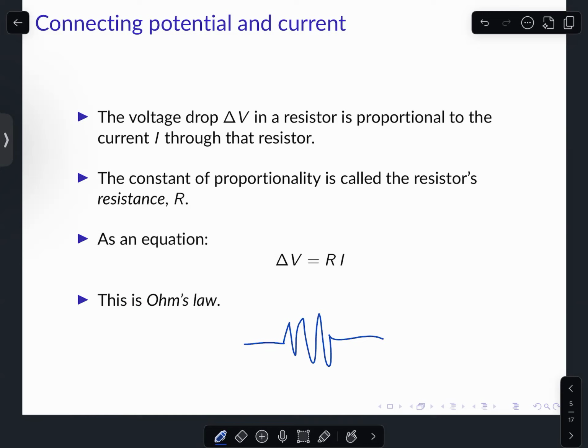Okay, so let me divide both sides by I and interpret this in a different way to give a better sense of this. What does it mean for resistance to be voltage divided by current? Here's another way to define resistance. Resistance is how much push you have to give to get a given amount of flow. How hard you have to push something to move at a given rate. How hard you have to push something, voltage, to get a given amount of flow.